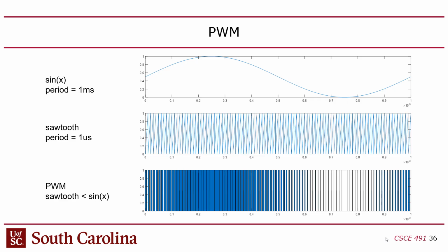You set the frequency there, and then to generate the PWM signal, really you just have a comparator where you compare for every time step, the time step being the rate at which you're updating the output PWM signal. For every time step, you just compare the input signal that you're modulating.